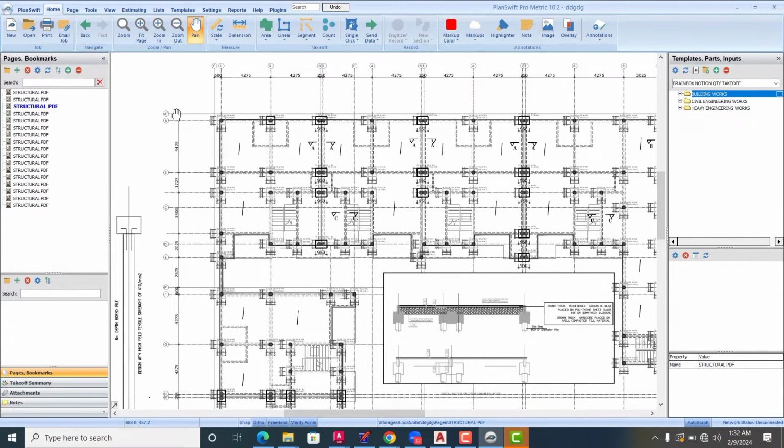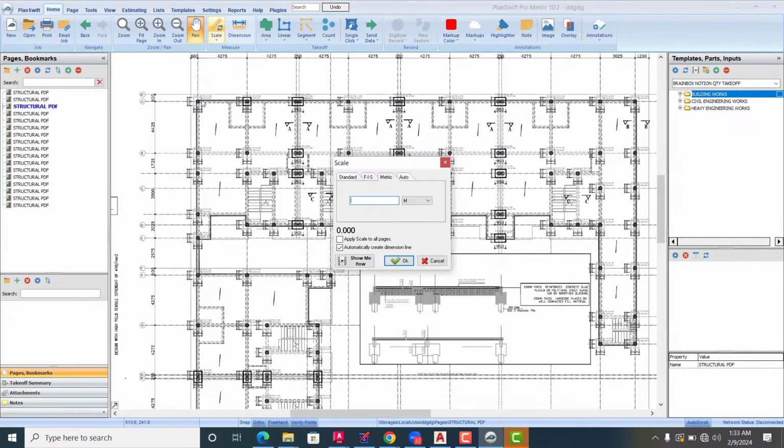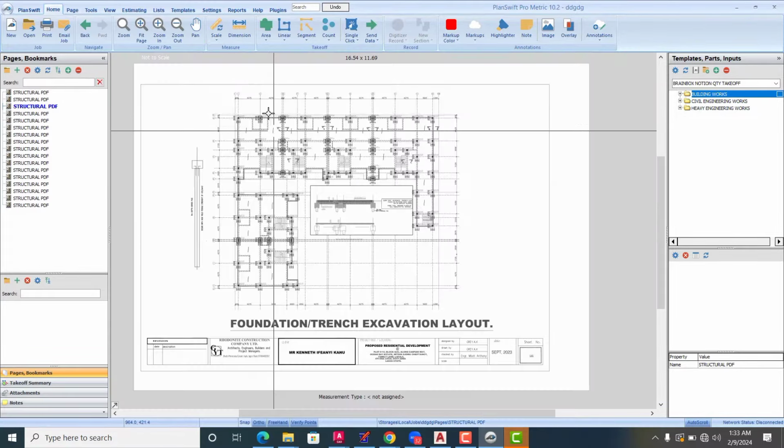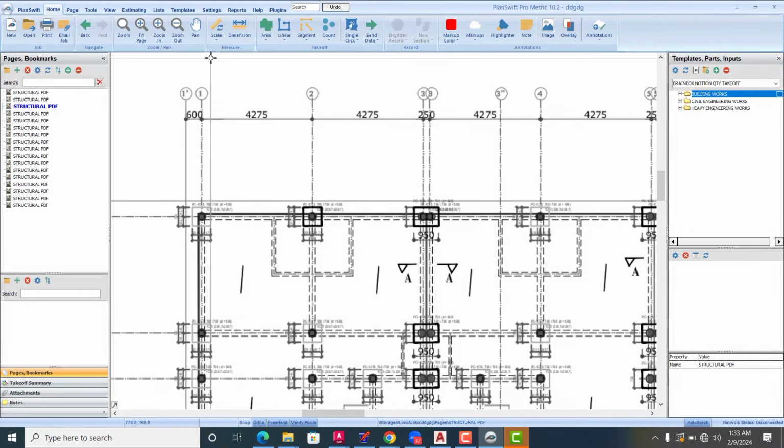Like I said, the first thing you do is scale your drawing. This is where we had issues that day. Scaling the drawing is very important, and you must scale in meters, because if you scale it in millimeters, you are going to have a lot of issues. That is why we were having values that were not corresponding to what we wanted.